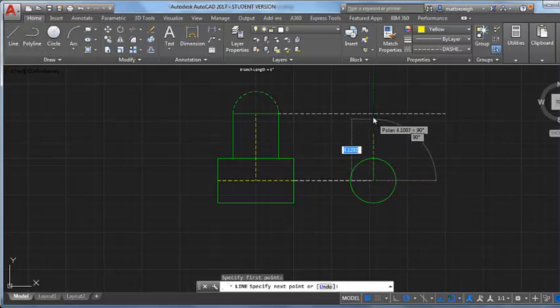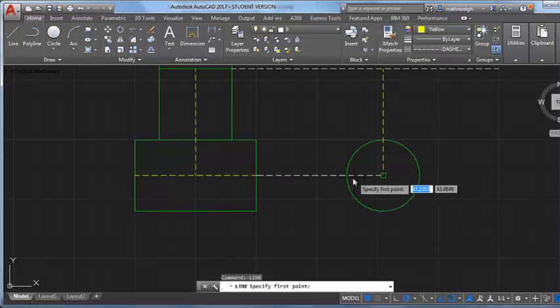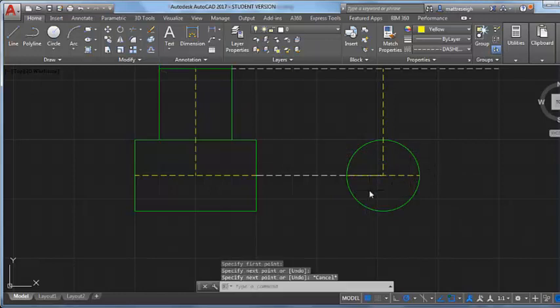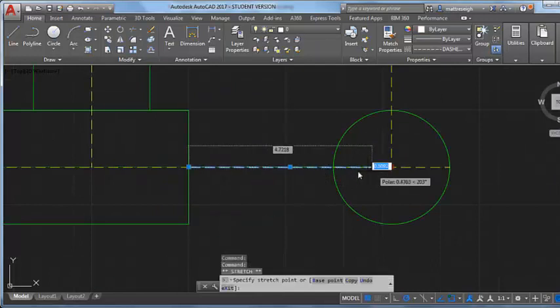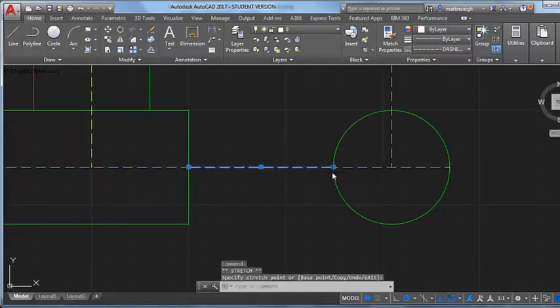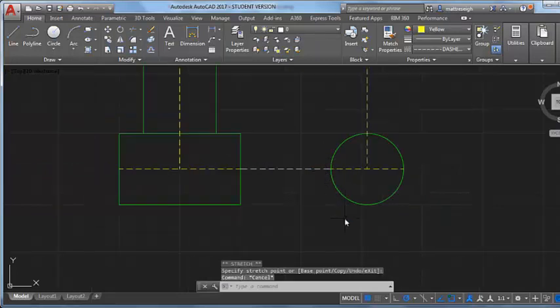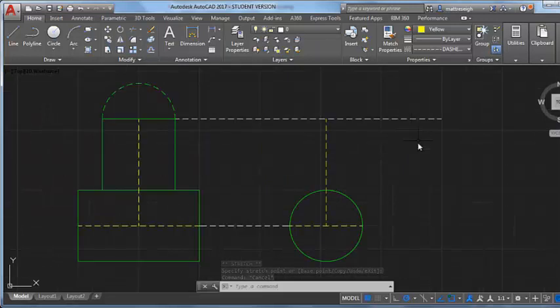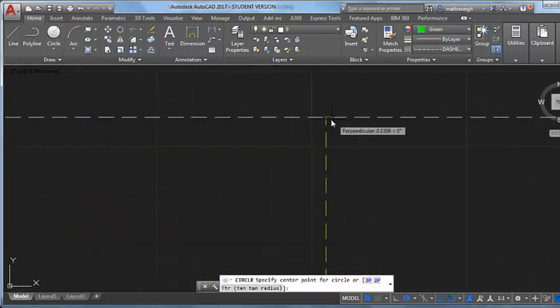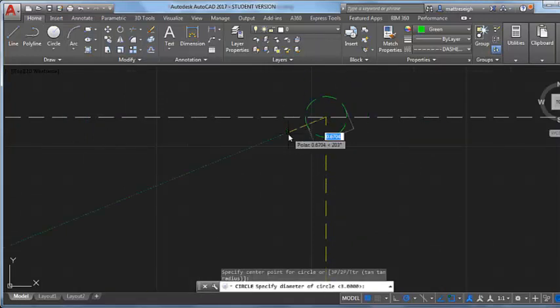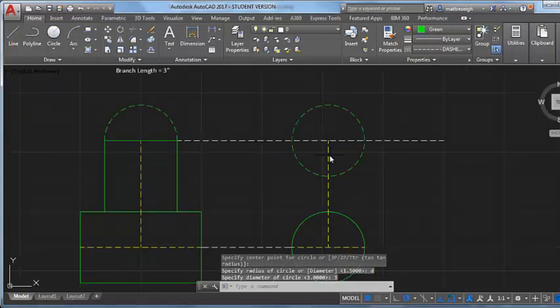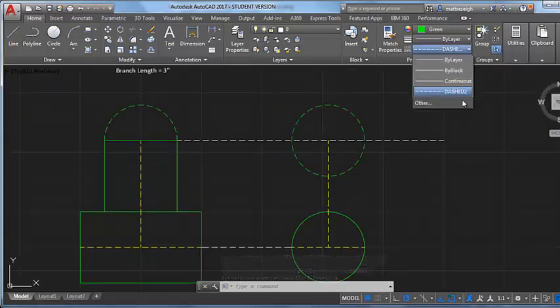I've got my center line here of my branch that I know goes up to there, and sometimes I like to draw in my center lines here just for my own reference. Actually, this line probably could have stopped here. It's just an orientation line, a projection line. So there we go. And this one I'll probably trim back once I put in up top a development circle with a diameter of 3-inch tube. Great. And let's draw that down to where it meets the header now.